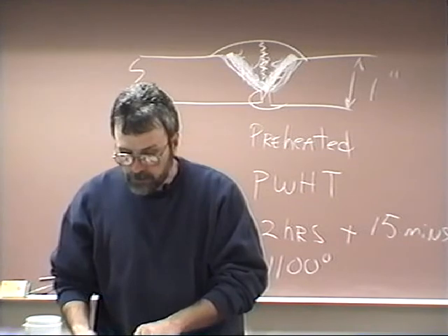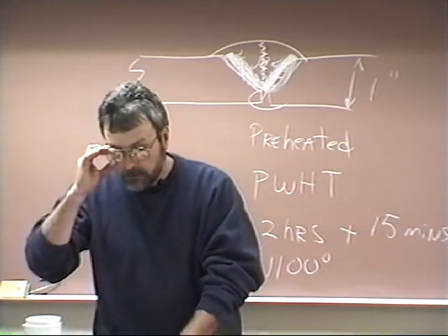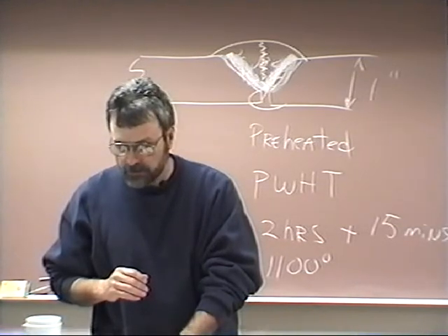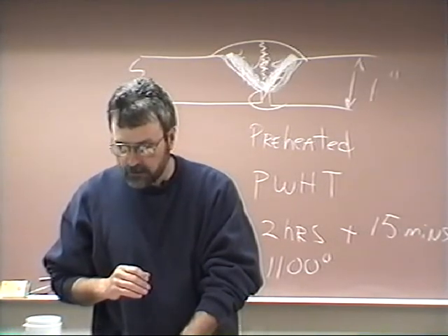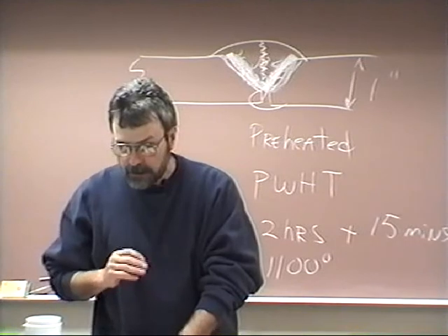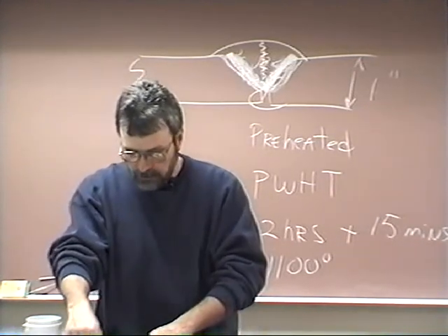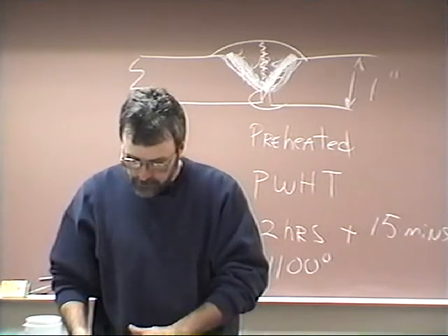A weld that is fully prepared should be as follows. The prepared cavity surface must be smooth without peaks and valleys. All traces of oxide must be removed. All spatter and globular deposits in the weld during each welding pass should be removed repeatedly. So you want to make sure you do all of that before you make the final repair.